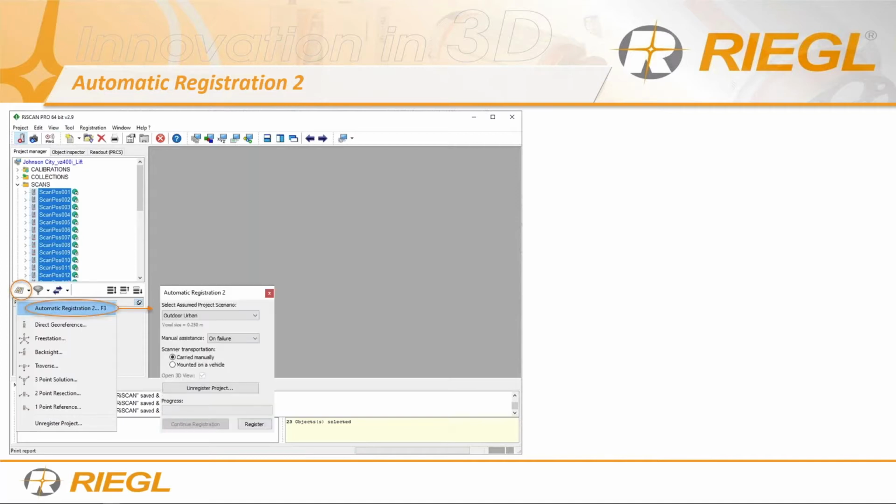And then once you select automatic registration, you'll get a display box or a prompt, and it asks you a couple of simple questions, right? So, what scenario are you doing? As you can see here it is outdoor urban. This is the project that I will show you later, which has a smaller voxel size versus if you were to go outdoor non-urban, it'll have a much larger voxel size.